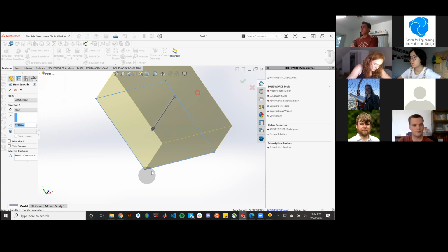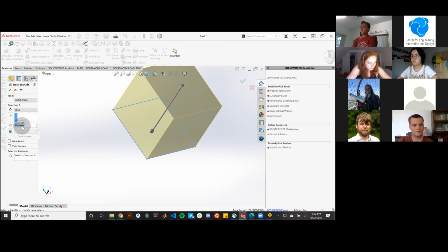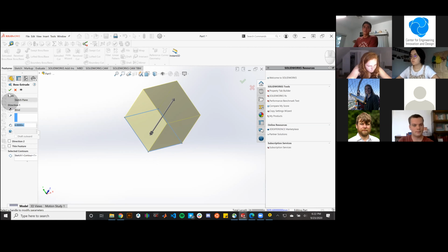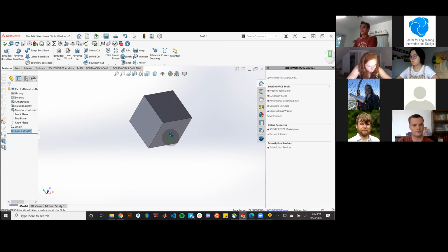But kind of like dragging a sketch around, that's not very robust. So in order to actually dimension it firmly, on this left-hand side, there's this little dimension area, and I'm going to again put in 6 inches. So once I do that, I can press on this little green check mark on the left-hand toolbar, and that's going to finalize it. So great, we now have a cube.